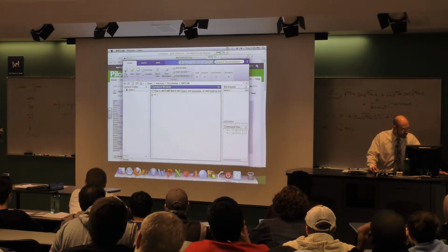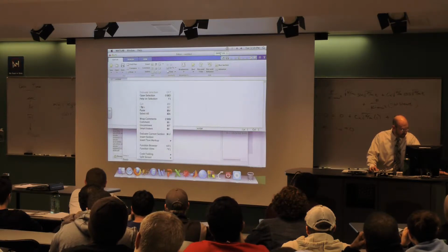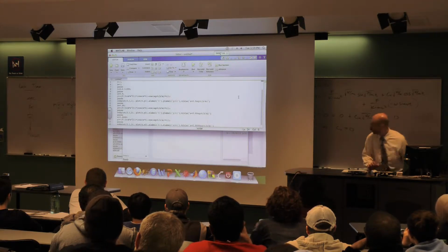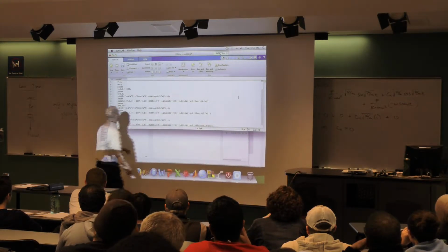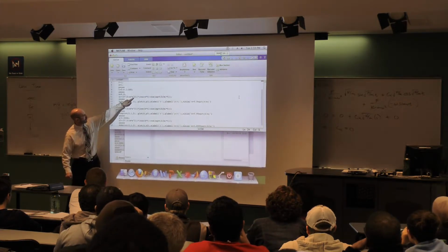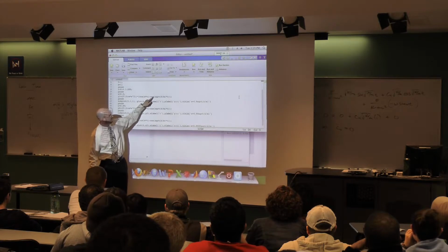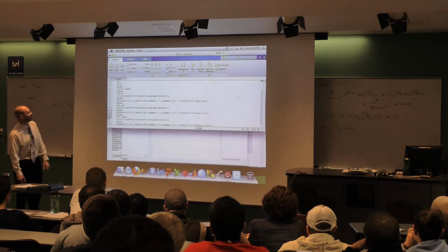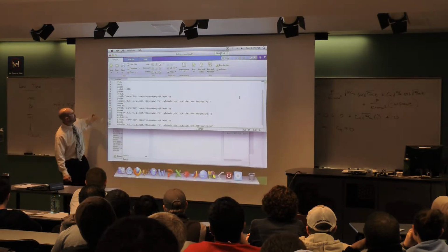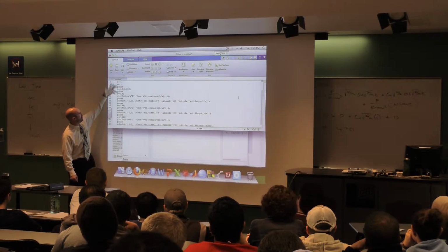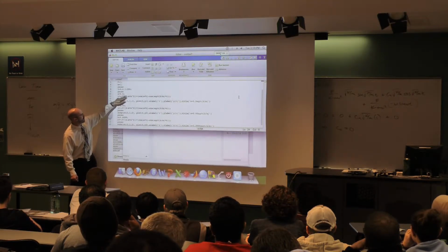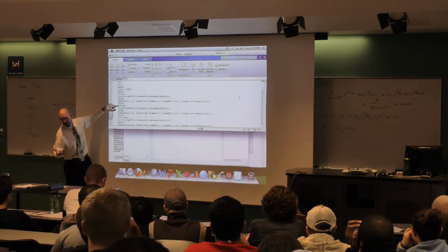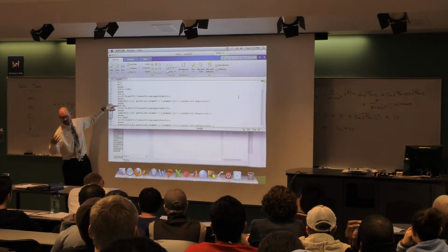See if I can run this. This is up on the page, so you can run this yourself. What I did was just code up the answer. This is it right here: F divided by k minus m omega squared, times cosine omega t minus the cosine of square root k over m t. This is the answer. I'm going to plot this for 3 values of omega. First, set all the parameters equal to 1: F is 1, m is 1, k is 1. Then we'll take omega compared to root k over m. If everything's 1, then root k over m is 1.